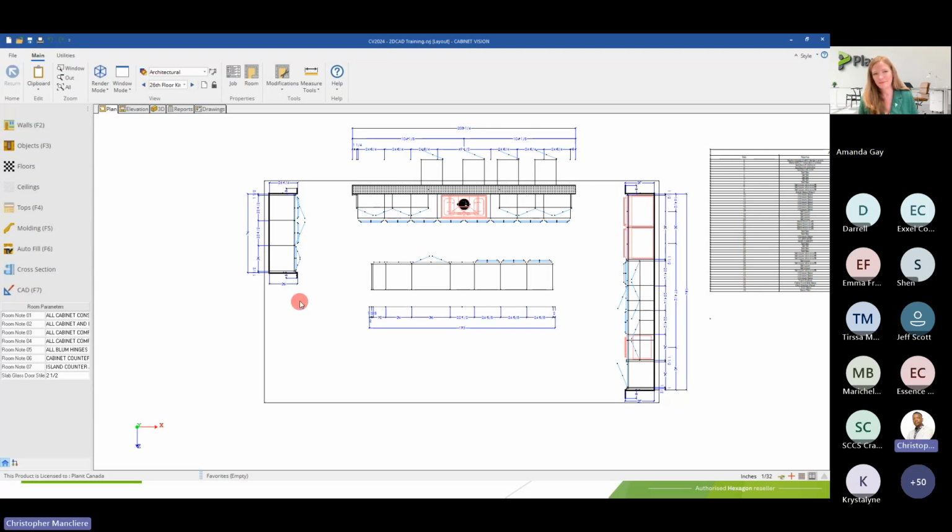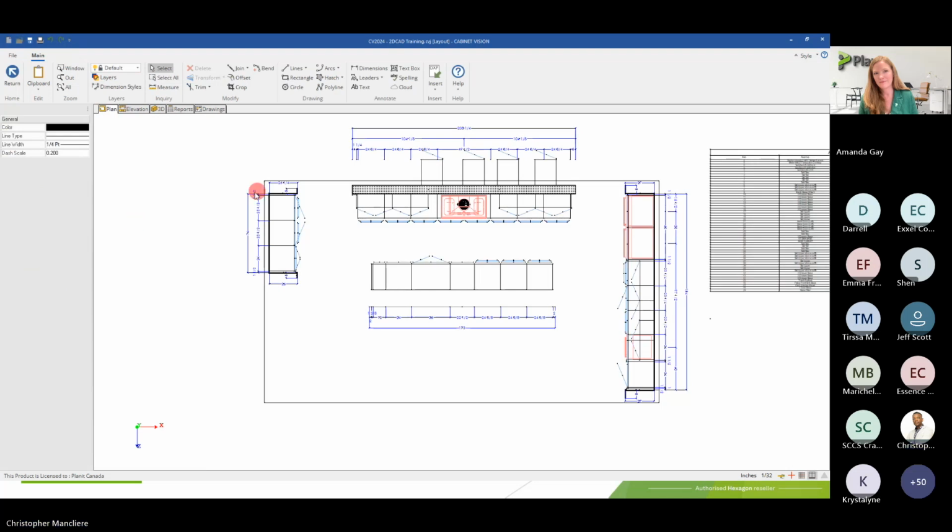Yes, absolutely. So when you set the dimension, the same way you do it with the text size. So if I go back to my CAD, if I go dimension, I can select tailed, so it's important to not place any dimension just yet. You just hit dimension and go directly to change the dimension type, and you'll select, for example, linear tailed.